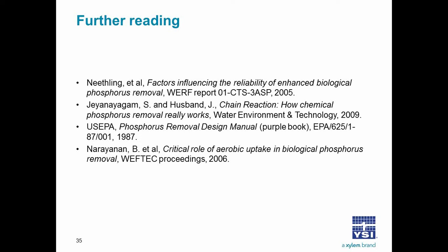For the uptake portion of it, of course, increasing the aeration rate in the initial oxic part is very important. If the phosphate uptake does not occur in the initial oxic part because of insufficient DO, many times there's no possible way to catch up. So it represents an opportunity lost and a limit to the amount of phosphorus that can be removed.